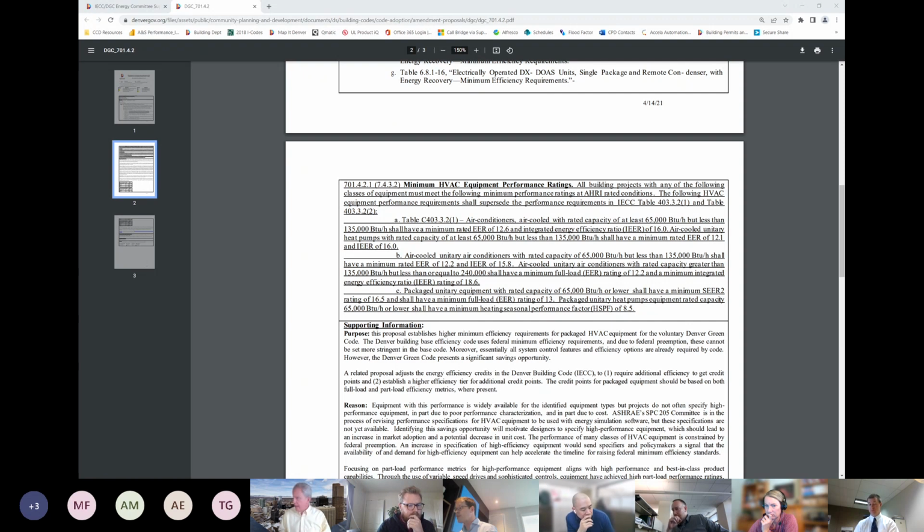Great, I encourage that. About the only other thing I would do here is just what you already pointed out, Elizabeth. Let's limit that to air-cooled equipment for now. And to address, somebody asked about evaporative cooled. This isn't really evaporative in this context. It's not evaporative cooling, you know, quote unquote swamp coolers. This is simply a packaged unit that sprays water on the condensing coil to take advantage of local conditions and, you know, wet bulb versus dry bulb condensing temperatures. I don't think that would be the intent for this measure, which is trying to push the limit on this simple packaged equipment. So I would leave the evaporative cooled out of it, but define C as including air cooled only.